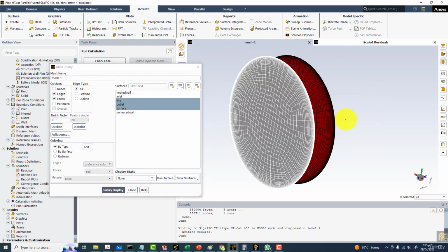On the surface we are going to find the bulk temperature, and on the line we are going to find the surface temperature. Then we put this into the equation, where we put the heat flux as the numerator, divide by Ts minus Tb, and we get the convection transfer coefficient.